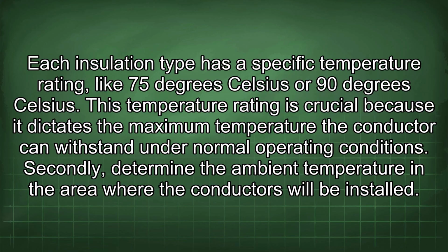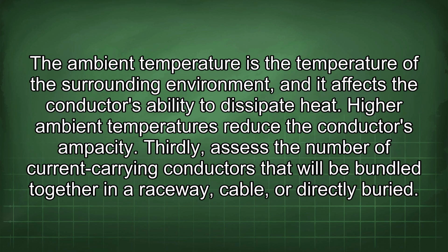Secondly, determine the ambient temperature in the area where the conductors will be installed. The ambient temperature is the temperature of the surrounding environment, and it affects the conductor's ability to dissipate heat. Higher ambient temperatures reduce the conductor's ampacity.